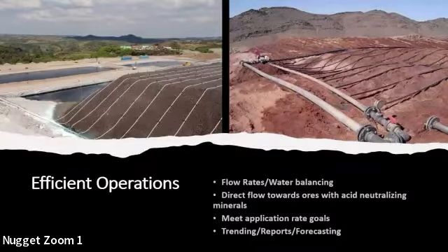One of the things that this has allowed us to do is improve the efficiency on leach pads. So you're not pumping raffinate or solution into areas that don't need it. You can route it around. You can see that you've got the side slope. Make sure you're not sucking a lot of your solution and it's being wasted here and it's not being distributed up there.